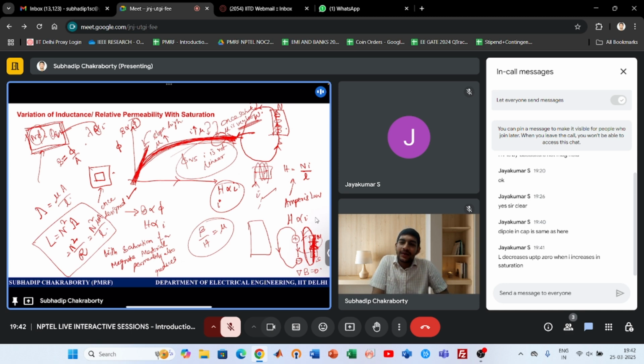Yes. And you must check the data sheets or the application notes of some company like Coilcraft or some other company which makes inductors, or Delta. You can just check their application notes. You can see the workable range of currents. After that, obviously, that coil will burn out, but before that, your core enters into saturation. And once your core enters into saturation, what will happen? The inductance offered by that system, or the material which is designed to give a particular inductance value, also changes. So for inductors, you see the application notes.